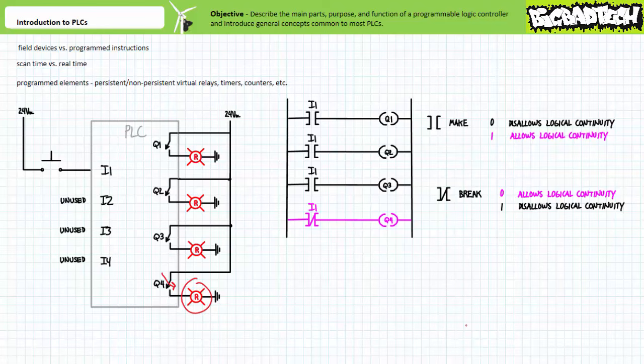The ability of a PLC to shrink the footprint and sheer mass of the controller is often reason enough to upgrade from traditional hardwired relay-based ladder logic. In addition to this benefit, PLCs are more reliable, flexible, powerful, cheaper, faster, facilitate troubleshooting, and can communicate more effectively and perform advanced data processing functions. As if that wasn't enough, if you don't like what a PLC is doing, you can always change what it's doing by reprogramming it without the messy necessity of physically rewiring it.